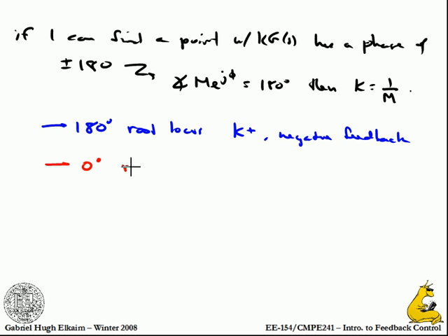If I look for the 0 degree root locus, this corresponds to K as negative or positive feedback, which under normal circumstances is destabilizing. However, because in this case instead of being 1 plus GK, it's now 1 minus GK, GK is equal to 1, not minus 1. So I'm looking for 0 degrees instead of 180. That's sort of how it works.